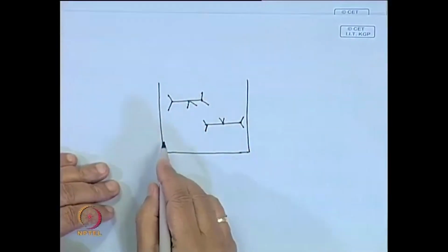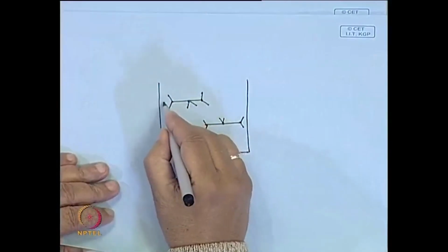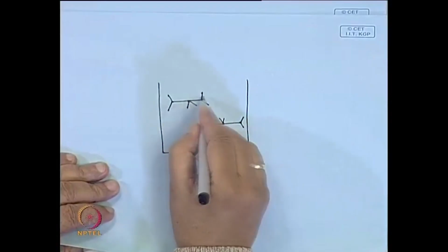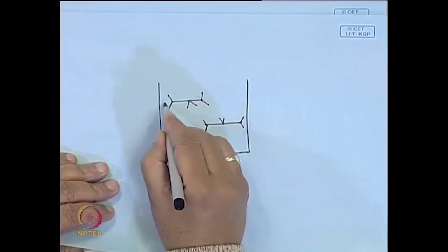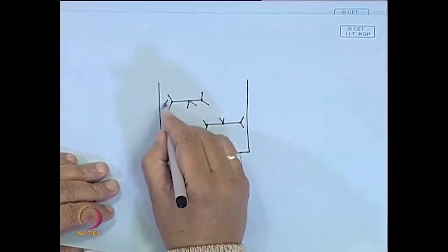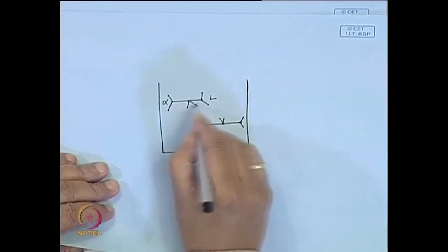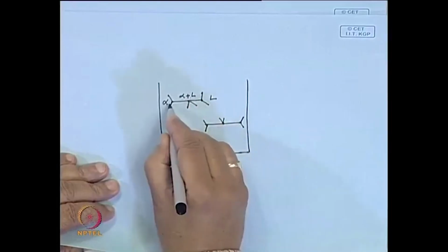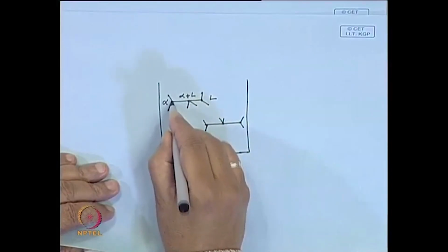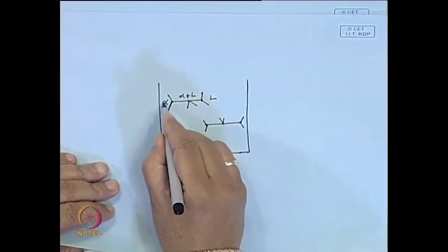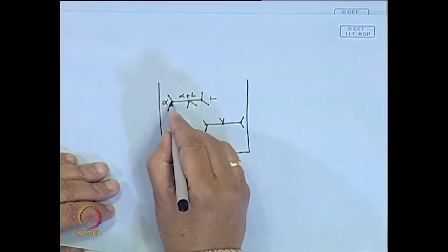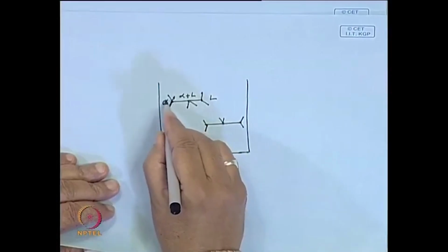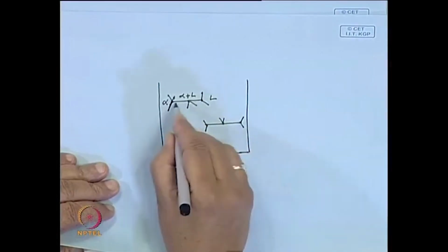Then you follow certain rules, like two phase regions should be separated by single phase regions. So, suppose this is alpha, this is liquid. So, this is two phase, and if you extend this line, which is the boundary between a single phase and a two phase region, it should extend in this portion here. This cannot go to a single phase region.